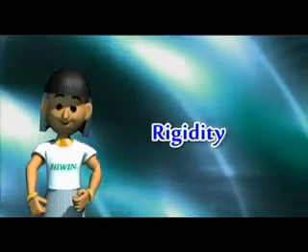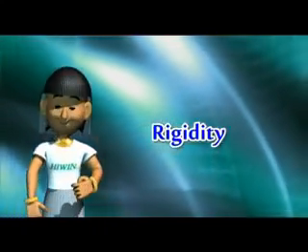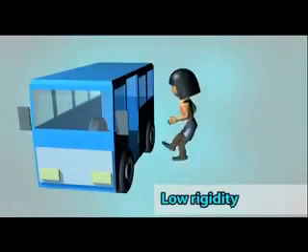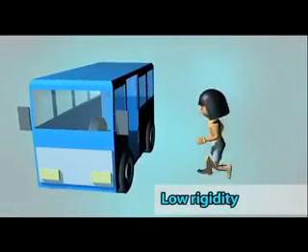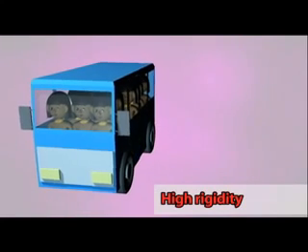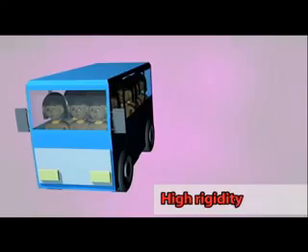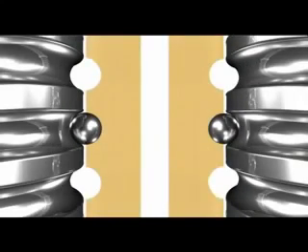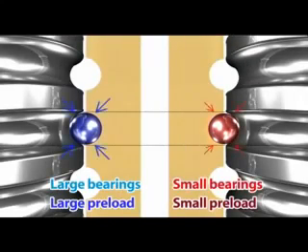Rigidity. Let's use another example. When a person leaps onto an empty bus, the bus will experience severe rocking. In contrast, when a person leaps onto another bus that already contains 30 passengers, the bus will not rock much at all. The use of slightly larger bearings in a ball screw will create preload, ensuring greater rigidity. The use of smaller bearings will reduce the amount of preload, and rigidity will also decrease.